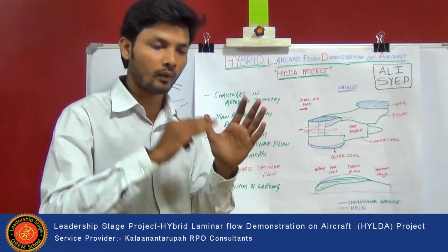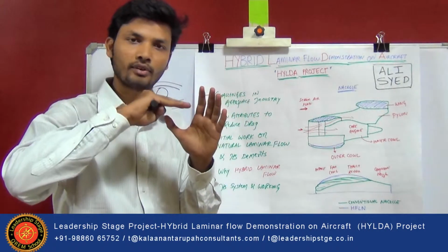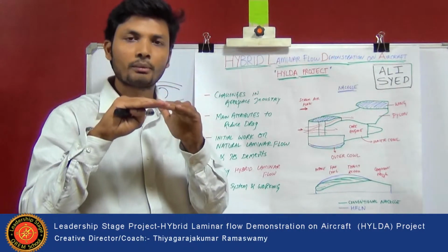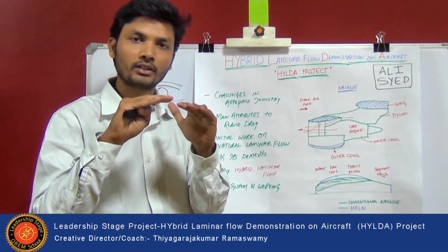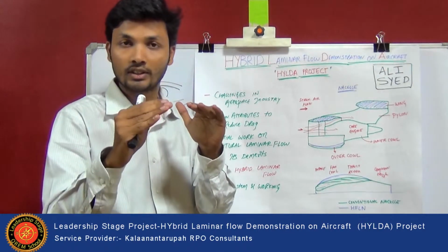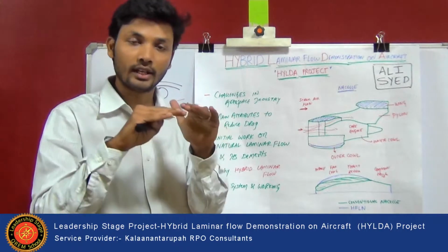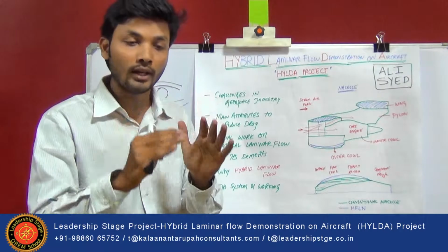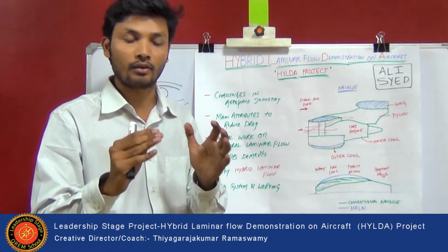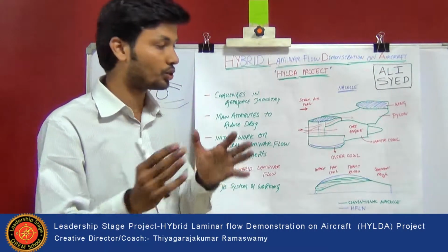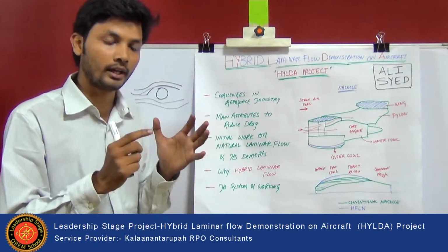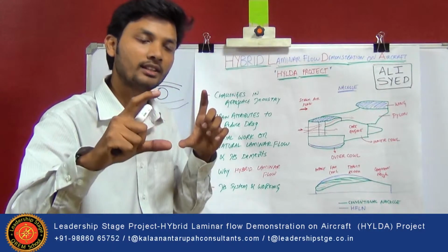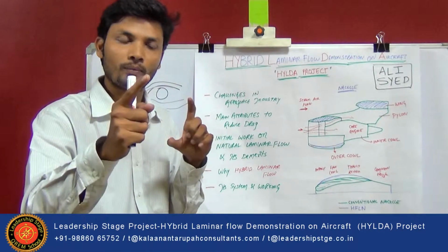As here you see the nozzle, the air flow cuts from the lip section of the nozzle and goes on. If there are disturbances in the surfaces, if there are any concave or convex dents on the nozzle, or any improper design or changes in the structure, it will give a spillage drag, which causes shock waves. So the most important thing here is that they firstly try to design the whole profile of the nozzle in such a way that you get the laminar flow.